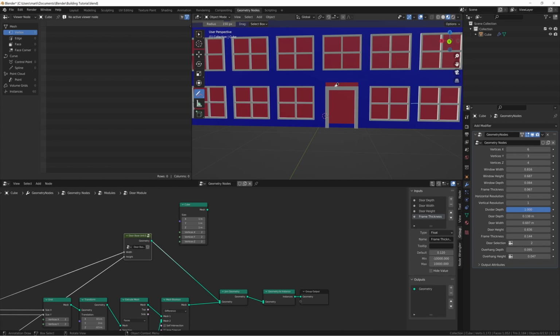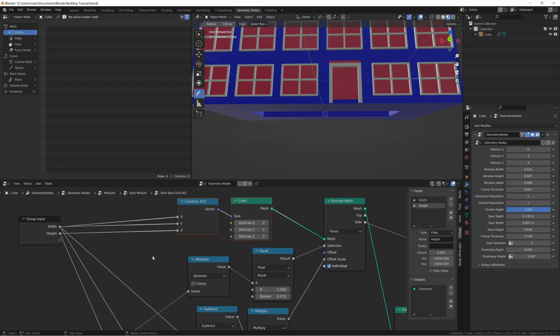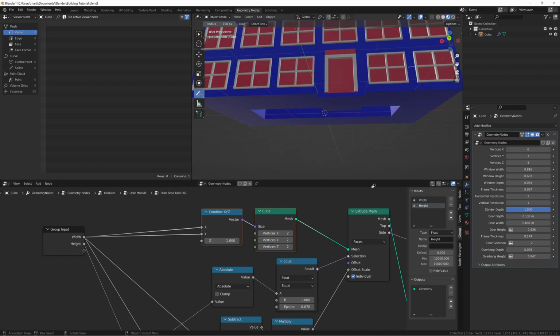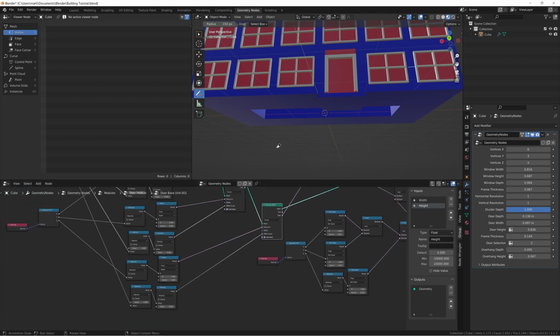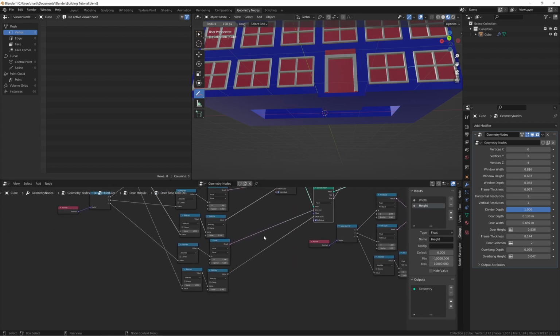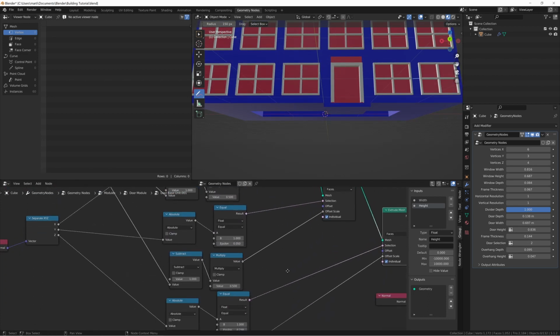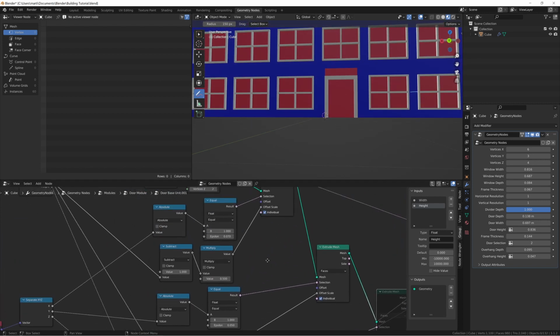And you know what? It's almost correct, but that's where the modifications come in. So first thing we want to do is just come in here and get rid of the height input right there going into the original cube. And we'll just set this to 1, which makes it a little bit too big because it's extruding based on what we did before over in this extrude mesh. It's extruding along the z-axis, but it's already the proper height, so it's just going to do a little bit additional here, which we want to get rid of. We only want it to extrude along the top mesh, as you'll see in just a second, but for now, I'll just hide this extrude mesh so that it's roughly the right height.